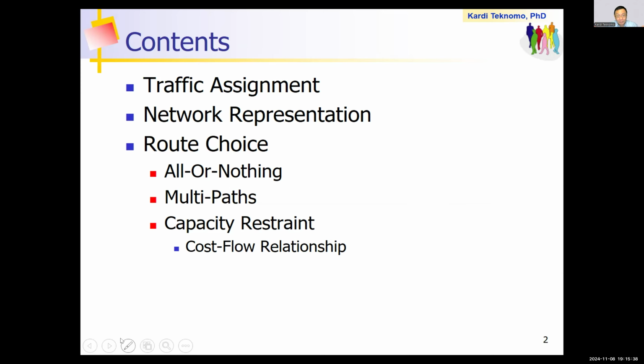So you will get link flow. It's no longer person trips. Now you will get the link flow. That is the purpose of modeling transport, to get the demand for each link. Of course, if you know the demand for each link, now divide by the capacity of the link, you will know the congestion. If you know the congestion, you can calculate the travel time, the delay, and other performance, including the energy usage, the air pollution and so on. All of this depends on one number, which is the congestion.